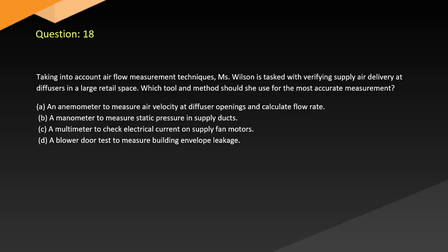Question 18. Taking into account airflow measurement techniques, Wilson is tasked with verifying supply air delivery at diffusers in a large retail space. Which tool and method should she use for the most accurate measurement? A. An anemometer to measure air velocity at diffuser openings and calculate flow rate. B. A manometer to measure static pressure in supply ducts. C. A multimeter to check electrical current on supply fan motors. D. A blower door test to measure building envelope leakage.